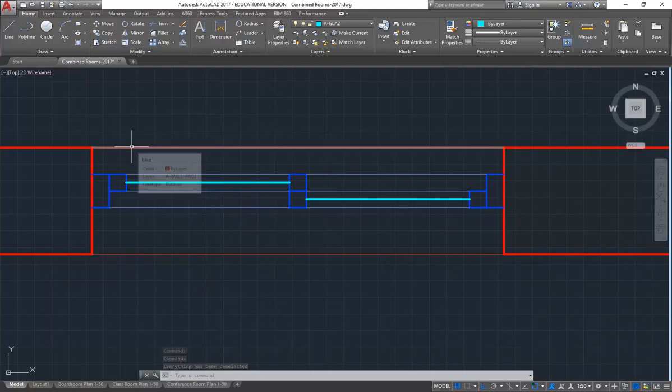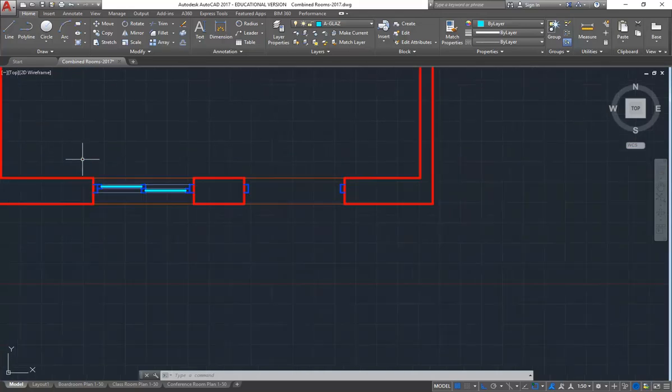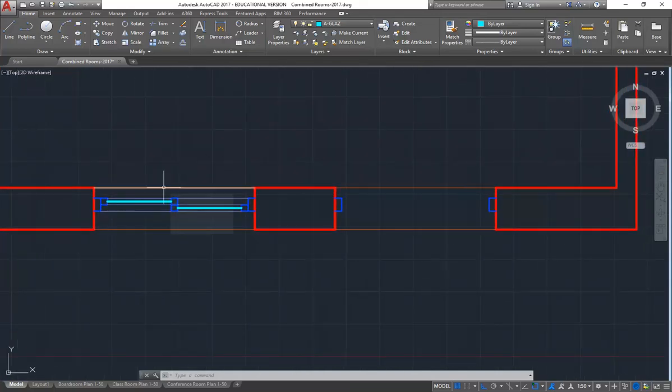And it's not only good drawing practice, it'll carry all the way through to construction stage. Because if you work out the opening sizes and get those right, then you're setting out the construction in the right way. Where a lot of people make mistakes with construction is that they try to measure to parts of the window, so they measure to the frame, when really you don't ever need to give that dimension. Like I've been saying, they're going to make the windows in the factory the way they always make them. You don't need to dimension the parts of the window or the parts of your door either.